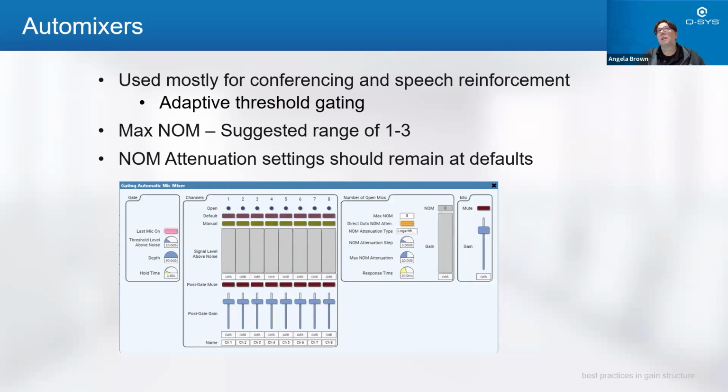All of the processing in the Q-SYS core, that is what I call live processing. In other words, it is processing the signal in real time, and the AEC block, the notch feedback filter, and there's a couple of others, are some of the most processor intensive things in the core. So yes, if you are looking at leaving the notch filter in line and working, you would definitely want to move it to the output side so that it's operating on a mix.